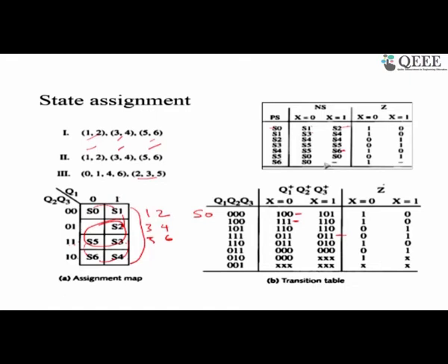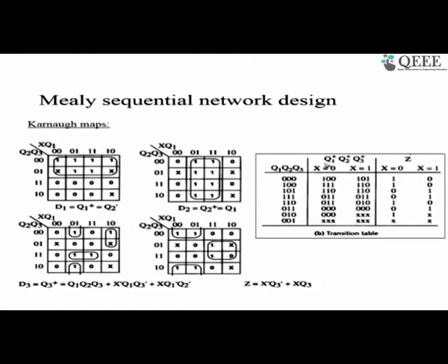Then we have to realize it. Realizing it can be done by constructing the K map for this one. We have encoded the states using 3 bits Q1, Q2, Q3. So this would be the present state. When you are in a present state, Q1, Q2, Q3 will take certain values based on the present state encoding. So that is what is given.